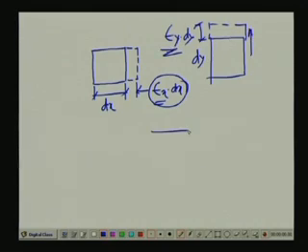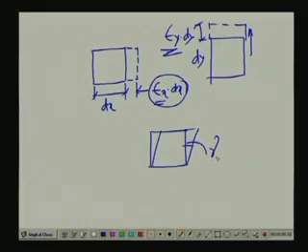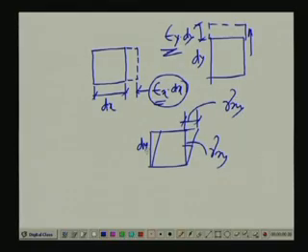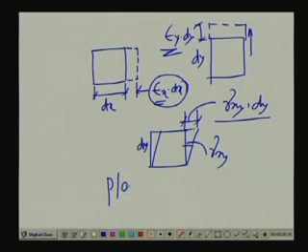Or if we have the shearing strain, which is gamma xy, then the extension is equal to gamma xy times, if we call this depth dy, gamma xy times dy. So, these are the extensional aspects when we talk in terms of the strain in the plane figures. These are related to the plane strain conditions.